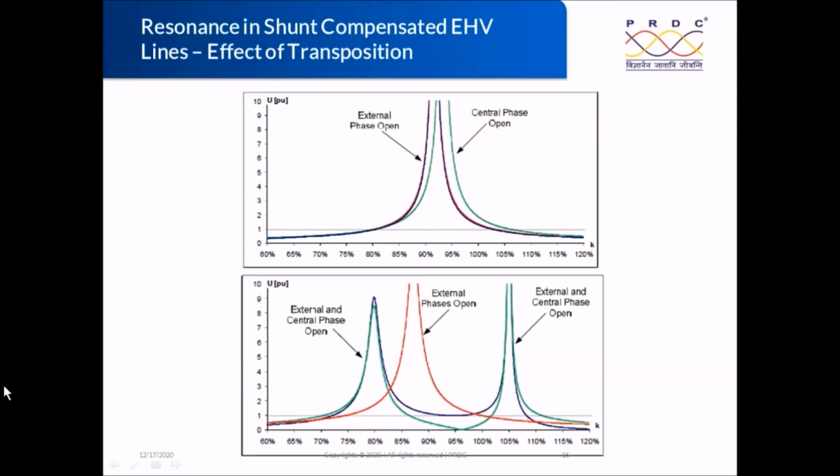This will again be, as I said, like saturation has high impact, but it could be medium or high, because if you compare with the transformers, the saturation knee point voltage will be much higher. Transformers have only 1.15 or 1.2 pu as the knee point voltage, but in the case of reactors, generally it will be at least 1.5 pu and above, like 1.7, 1.8 pu, because they use gap cores, so we have a high value to reach saturation.